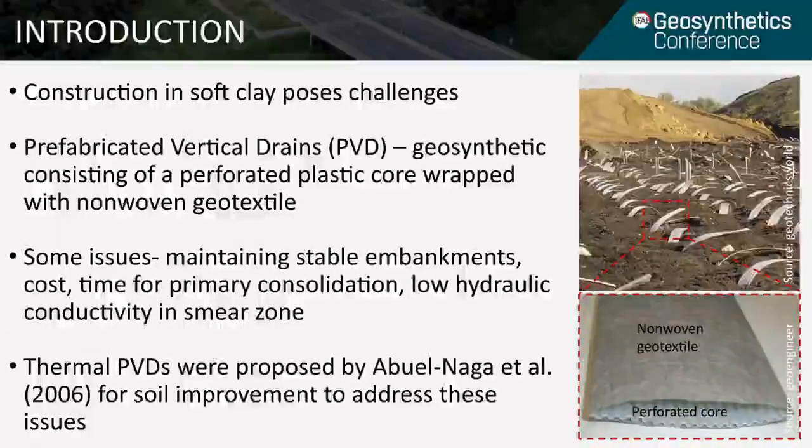However, there are still challenges when using PVDs, such as maintaining stable embankments, the cost, time for primary consolidation, and low hydraulic conductivity in the smear zone. So more recently, the use of thermal PVDs has been investigated as a method to overcome some of these challenges.